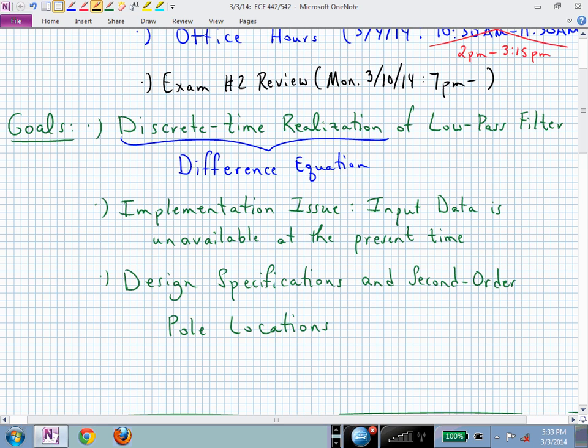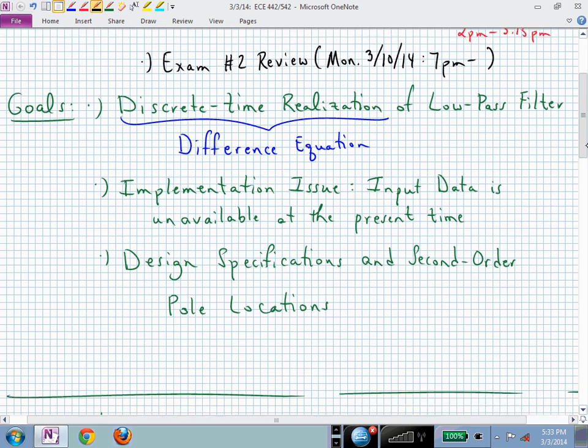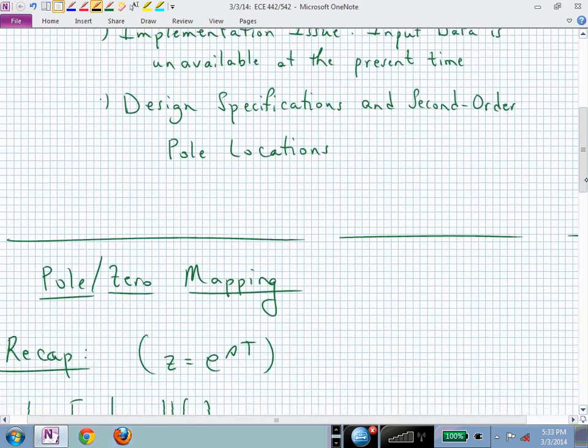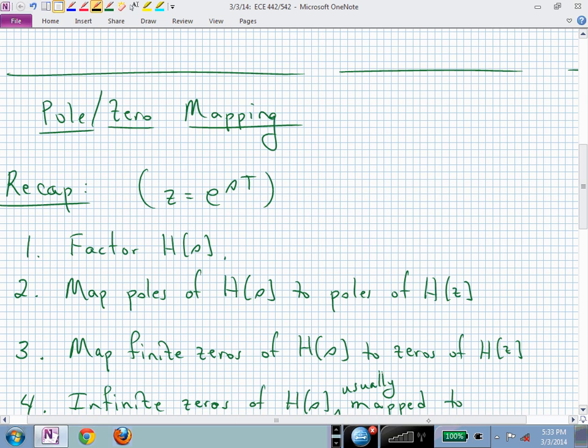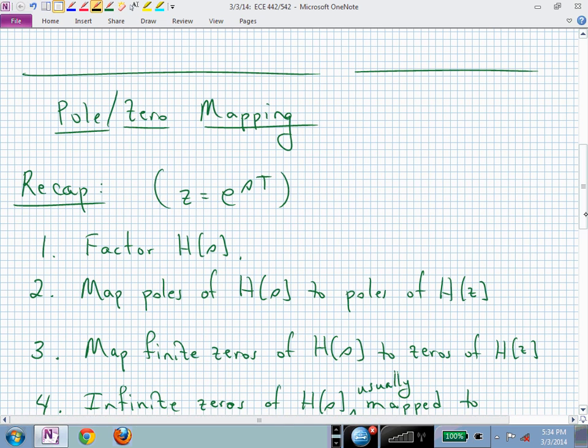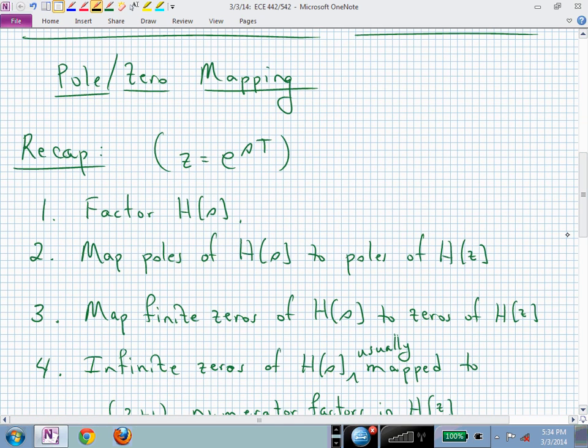When you put everything inside this very small region in the z-plane, those poles or roots or modes would be much faster. And the dominant behavior would be specified by those 2 dominant poles that are determined by your design specifications.